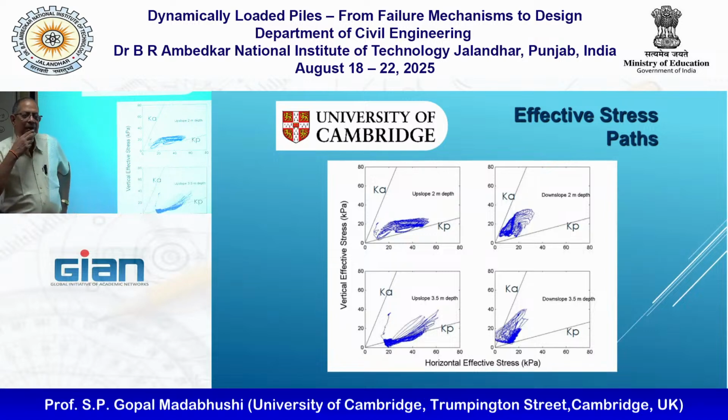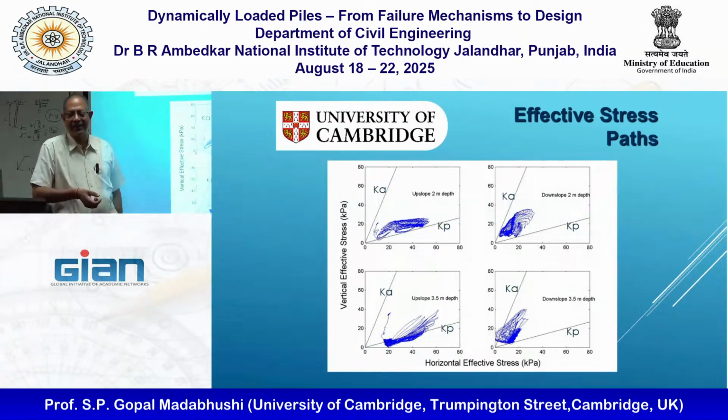So once you have good experimental data, you can get quite a lot of information on the soil stress state as well. And now if you do this, if you ask your Plaxis or Abaqus or whatever, plot me the stress path, then you know whether your code is working or not.